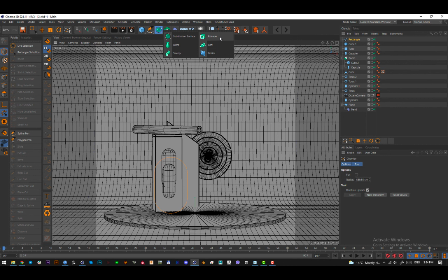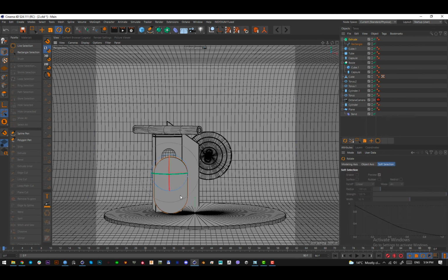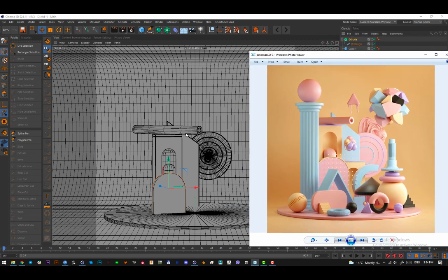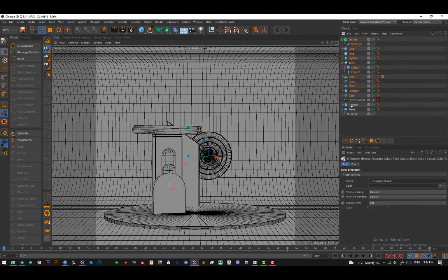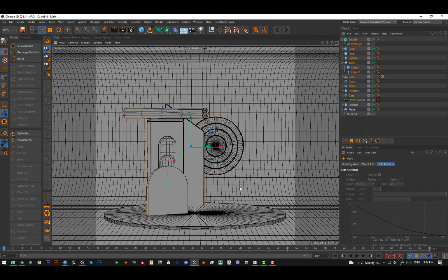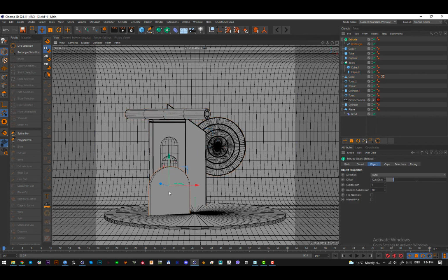Now while pressing Alt, click on extrude with the edited rectangle selected. It will create an extrude like this. Okay, put it here. Okay, this is perfect. Now when I look at this, I have a feeling that our elements are a bit too small. So let's just jump in here and select everything except for the cylinder and plane and scale it up a bit. Okay, this is better.